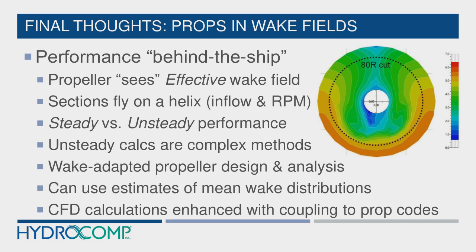where you add the induction effects, the propeller effects, or it's a total calculation and you deduct the induction or the propeller effects. Now, the latter is how we're approaching the coupling with Fine Marine, that they're giving us at an inflow plane a set of total velocity figures.